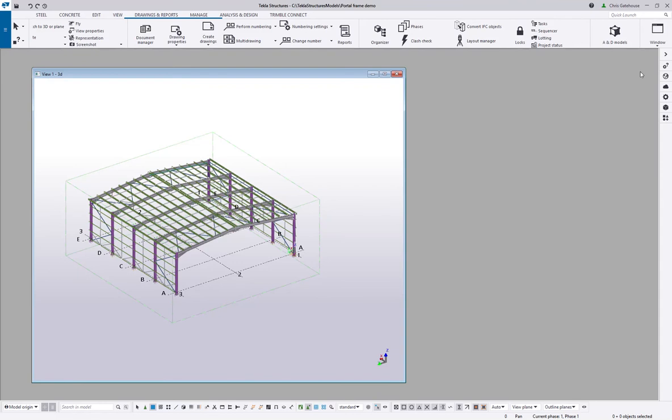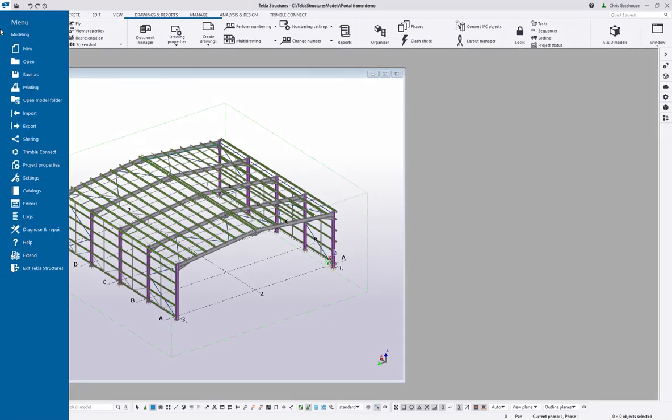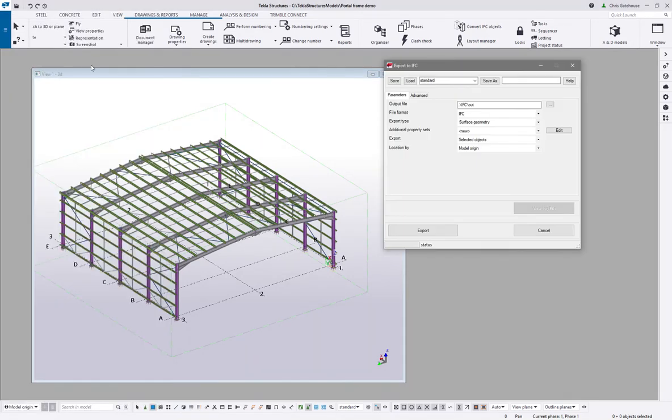Again, very straightforward. There's various exports as well, so you can export IFC files if you're familiar with BIM protocols, if that's something you're being asked to produce. So if I produce that as a coordination view 2, location there, and include all objects, I can export that now. We'll let that run. That's going to create me an IFC, which I can now view using Trimble Connect.